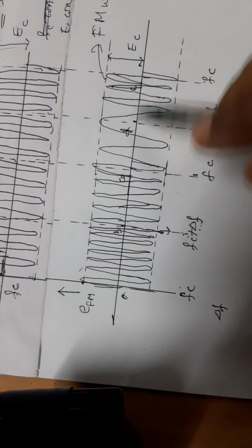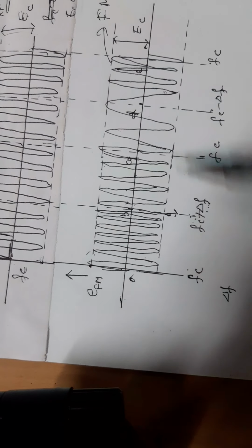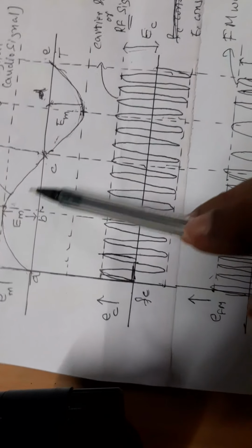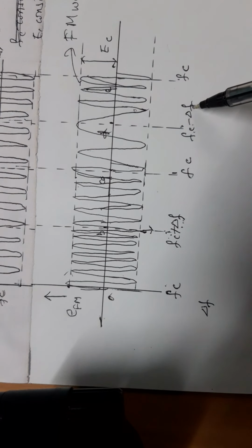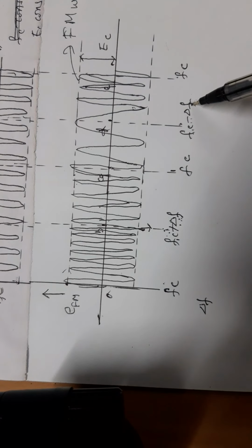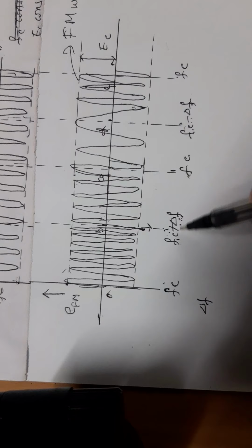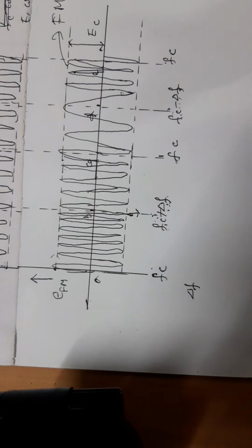So, you see, in a frequency modulated wave, the carrier amplitude is constant. Phase angle is 0, that is constant. Only frequency continuously changes according to the continuous change of the amplitude of the modulating signal. Now the frequency changes from Fc minus delta F to Fc plus delta F. Minimum frequency is Fc minus delta F and normal frequency is Fc, the mid frequency, and again it increases to Fc plus delta F. Therefore, delta F is called deviation from the normal frequency.